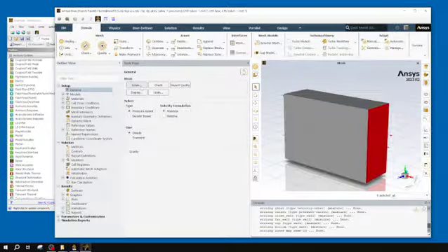These first mesh options, since we've already made the mesh, aren't too important. You can report your quality in case you're interested in that. But for the most part, you should be good to go. For my solver type, I do want a pressure-based. I want an absolute velocity formulation, and I'm going to be doing a steady state. If gravity is something you're interested in, you can add gravity into your simulation. Probably more important if you're doing water or something, but I'm going to be doing air, so that's not too worrisome.